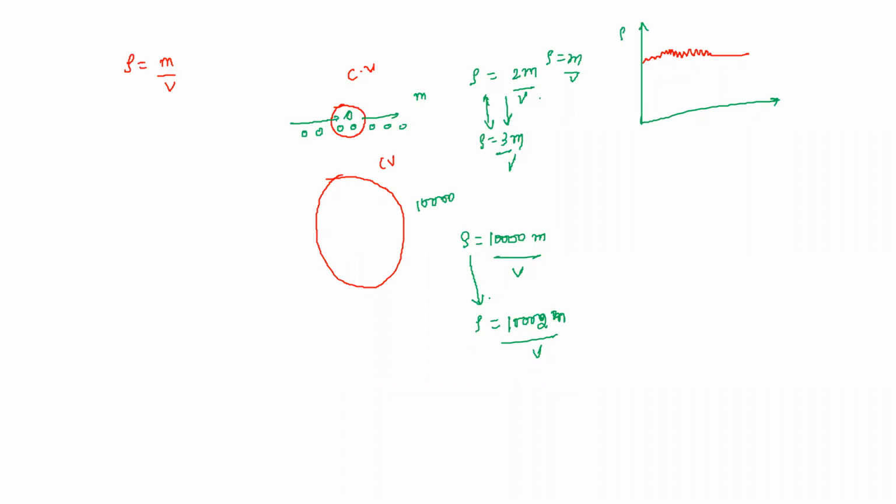That is why the control volume approach reduces to a control mass approach, unless there is a different kind of flow, an unsteady state flow, where there is accumulation. Molecules keep on getting accumulated. That's unsteady state flow, and in that case it would be a different story.